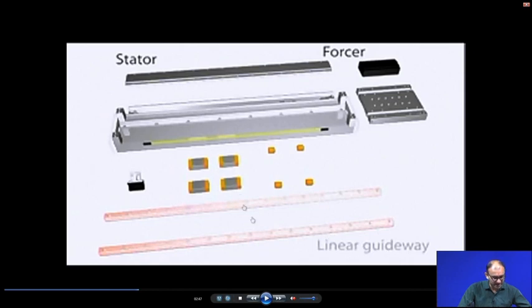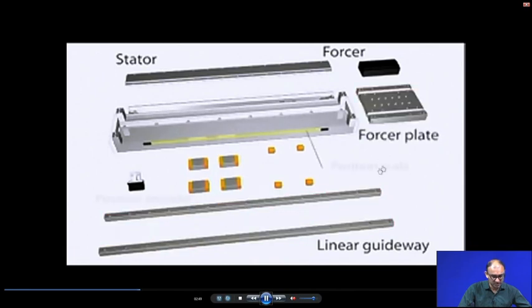And we need a linear guideway, because this is used just for movement, and after the movement you also have to calculate how much it has travelled from one location to another. So, these linear guides are very important, because the straightness and the linear motion, everything depends on the precision of this linear guideway. So, that is the thing.